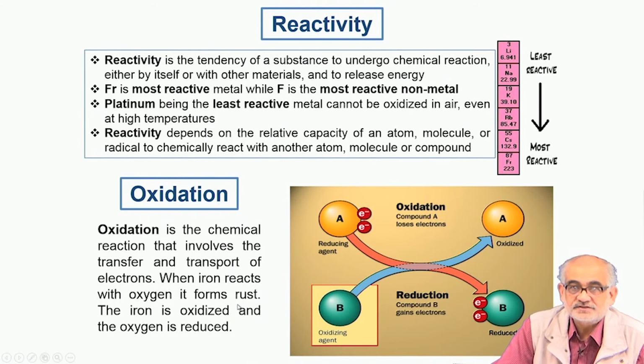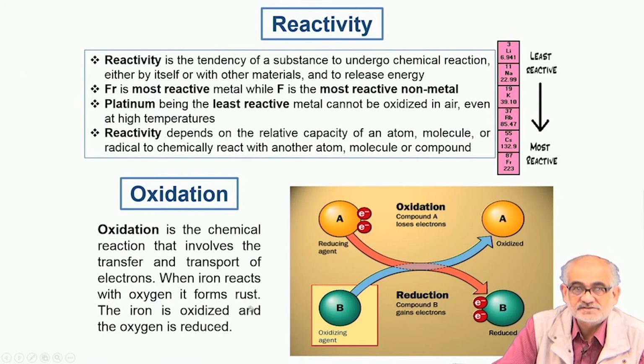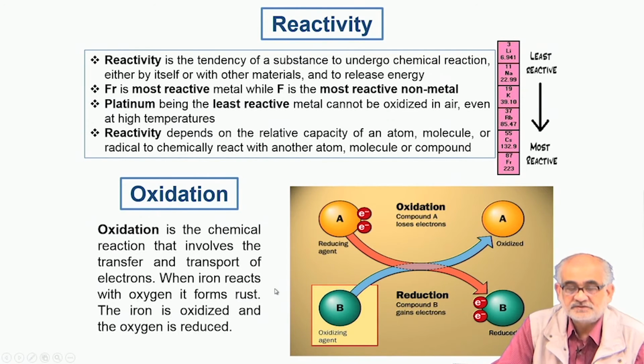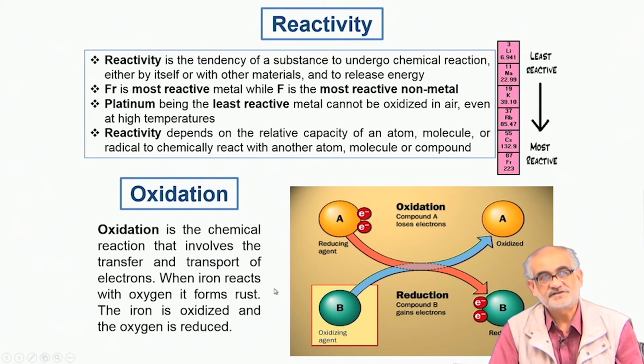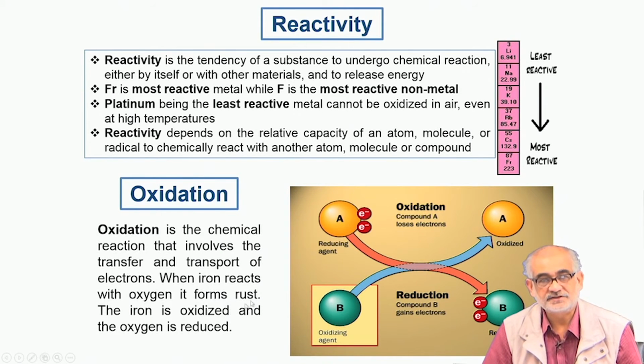It grows because it reacts with the atmosphere and forms certain hydroxides, and these hydroxides are fairly porous and structurally very different from the underlying substrate, because of which the rust spalls off the surface and exposes a fresh one, and that's how the process of degradation, or the rusting, continues.